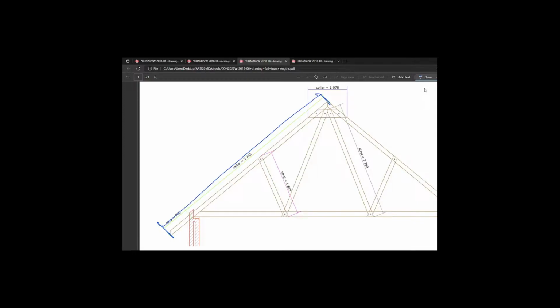So in the event that you're not given any of these dimensions, you'll just be given a diagram of the truss and a section scale. You'll take your ruler and you'll take it to the furthest point, as indicated here. So including this shaped end, you take it past right to the corner, and then with your ruler you measure right to that corner as well. Okay, so in this case for the strut, since we're doing the shorter strut at the moment, she's gone to this furthest point, which is that corner, and she's gone to this furthest point, which is that corner. She's used the ruler, converted it to millimeters, and came out to 1.87, 1,870 millimeters.